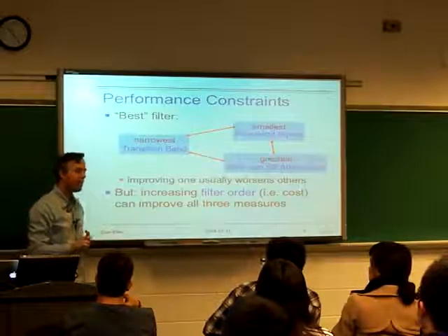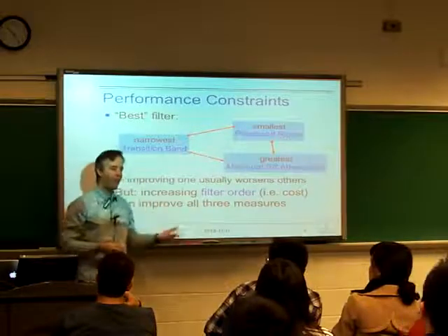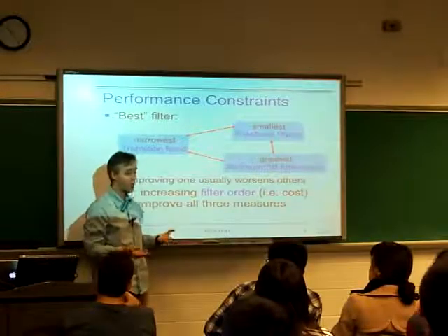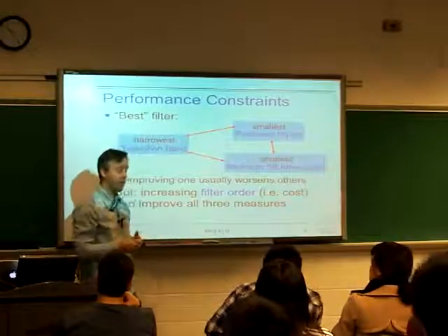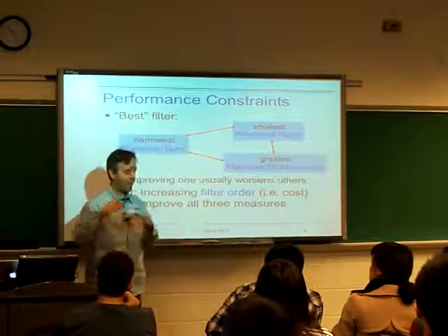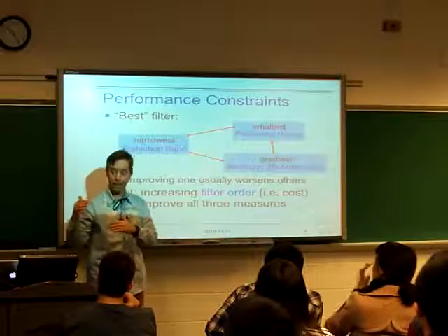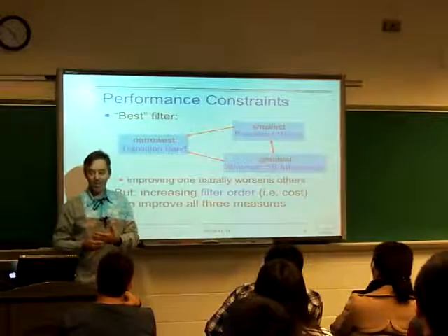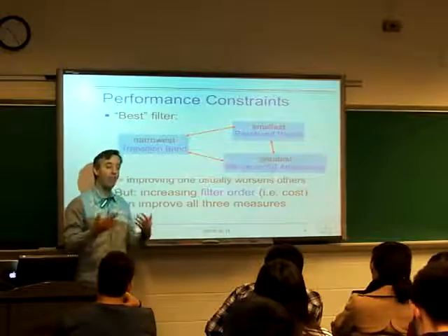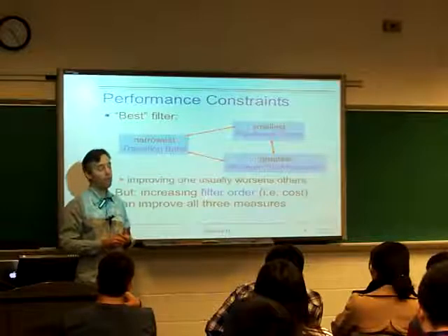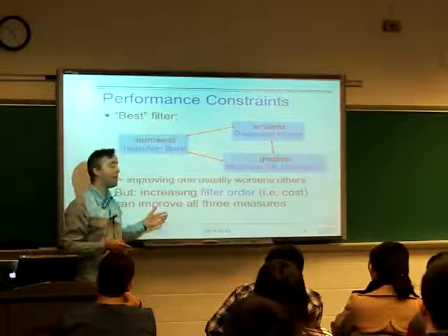That's interesting. We can use higher order filters if we're prepared to take the computational cost, if we have the layout space, or we have enough cycles in our processor to do it. But there is also a second order constraint, which is that eventually, if you get up to very, very high order filters, they do have stability problems, so it's not unlimited how far you can go.